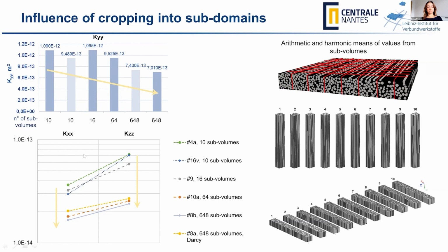So the same for the transverse permeability values here, you can observe with the exception of several values, but this is due to the use of not exactly the same technique. Because, for example, the result 8a was not a renormalization, but a Darcy simulation at macro scale. Macro means macro for this subvolume, for this sample, with the locally calculated permeability input before.